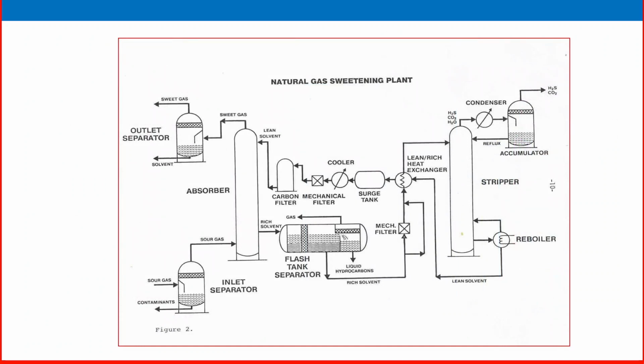So here is a more elaborated, detailed process flowchart. Look at that one. Absorber is there. Go ahead from the inlet. Inlet sour gas is entering from a knockout drum. The knockout drum is removing any unwanted material like moisture, water vapor, or solid particles, so only the pure gas component will enter here. So this is a very good system for supporting the performance of absorption properly, increasing the efficiency. This one is the inlet knockout drum.